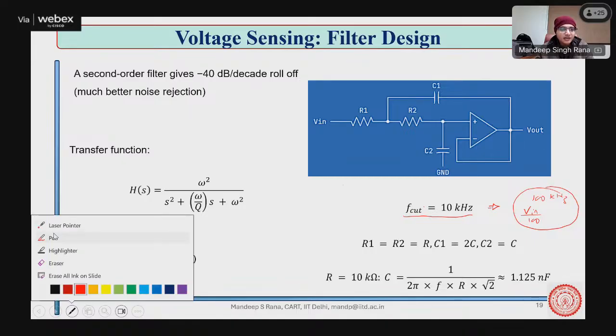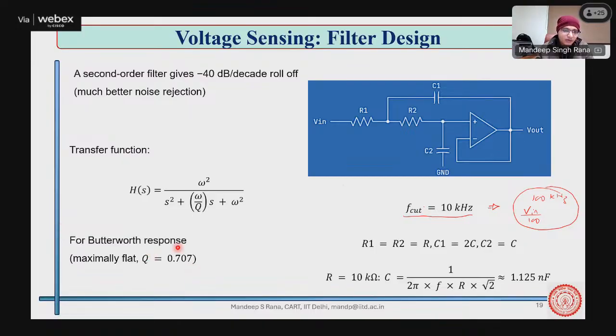So basically, any filter you are designing in BMS or for AFE should not have a lesser quality factor than this. Because if you go to lower quality factors, it becomes very sluggish. If you go to a much higher quality factor, it becomes another problem, things become underdamped, and more gain comes into the picture. So the quality factor should not be high, to avoid unnecessary amplification of some frequencies, and should not be very low, to avoid very slow operation of the filter.